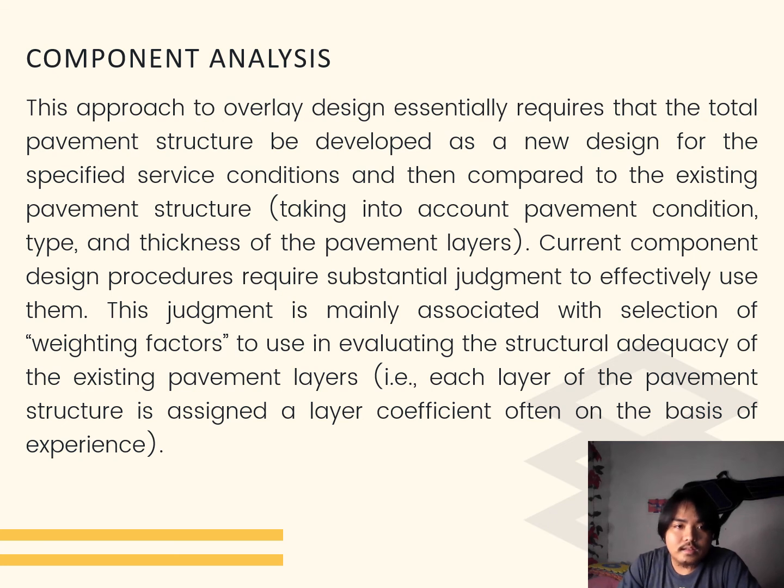Currently, component design procedures require substantial judgment to effectively use them. This judgment is mainly associated with selection of weighting factors to use in evaluating structural adequacy of existing pavement layers. Each layer of the pavement structure is assigned a layer coefficient, often on the basis of experience.